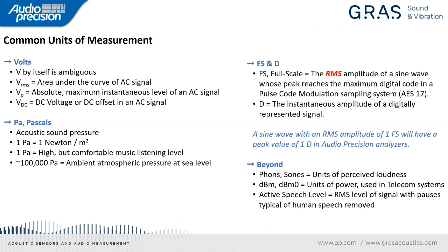And unlike volts or pascals, which are defined by an international standard, they're defined as SI units, FS is just an understanding, if you will. Everybody assumes certain things about it. The most common definition, and the definition that Audio Precision uses, comes out of an Audio Engineering Society standard, number 17. And it is exactly as it says.